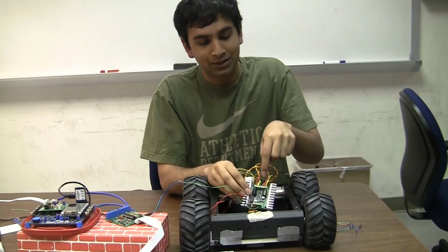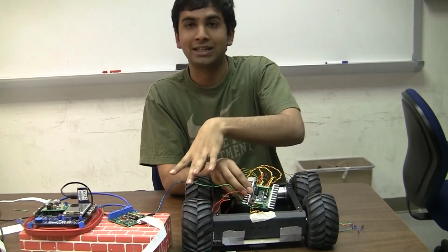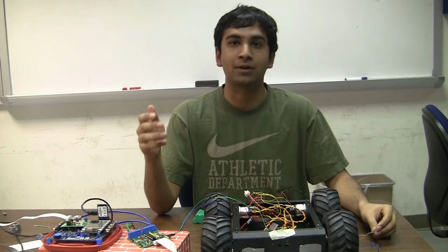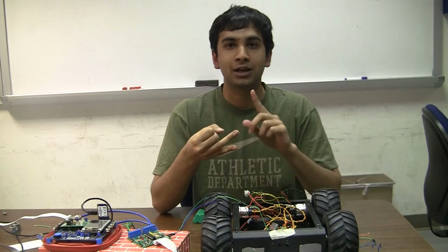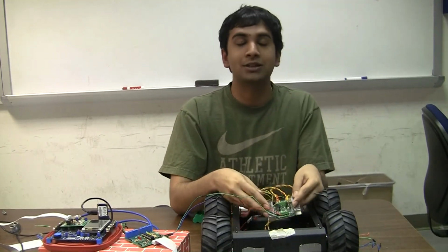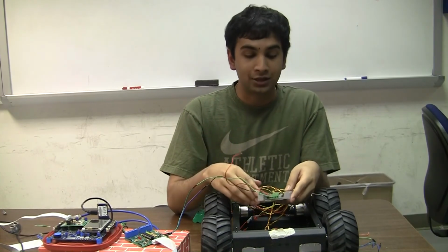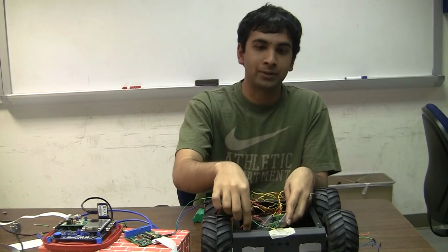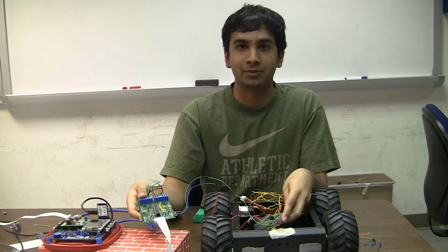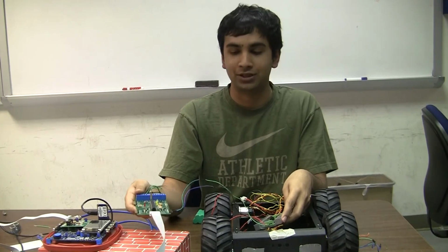These pins on the outside are basically connected to the encoders and the motors on each side of the rover. The motor PIC sends a packeted UART message, which includes an address, a command, a speed, and a checksum. This packet is sent to the Sabertooth, which translates it to the motors. The encoders are mounted on the front side of the rover, and I would have attached them to the external interrupts on the motor PIC. Unfortunately, we were low on time and were not able to implement this part of the project.